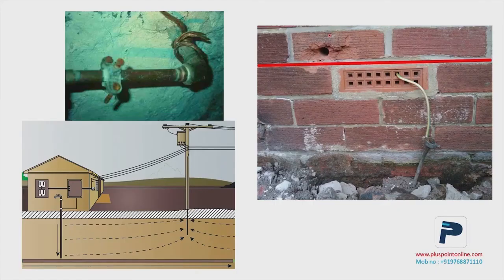In the case of water tap and pipe earthing, it is considered very dangerous because if, for example, there is a problem in a particular equipment at home, then even releasing water from a tap can cause a current in the water, and this can affect the water supply in an entire building as well. So these are the problems caused by the water pipe earthing method. It is a major problem and therefore it is recommended to avoid this method of earthing.